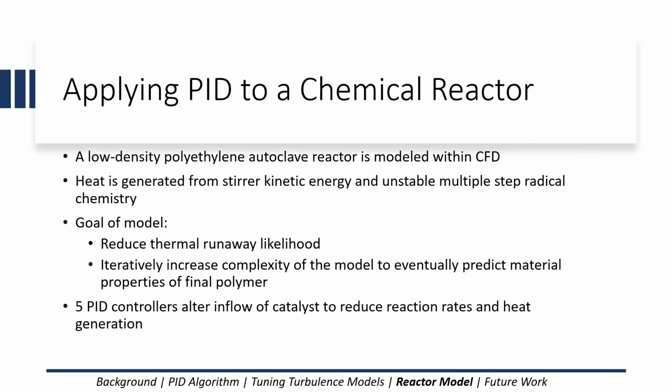To further expand on the usefulness of PID control within CFD models, a low-density polyethylene autoclave reactor was modeled within CFD. This type of reactor is prone to thermal runaway, so the CFD model had to reflect this scenario. Heat within the model is generated from kinetic energy due to the stir shaft and unstable multi-step radical chemistry from the polymerization process. The goal of the model was to understand what leads to these thermal runaway events and to reduce them through improving the process.